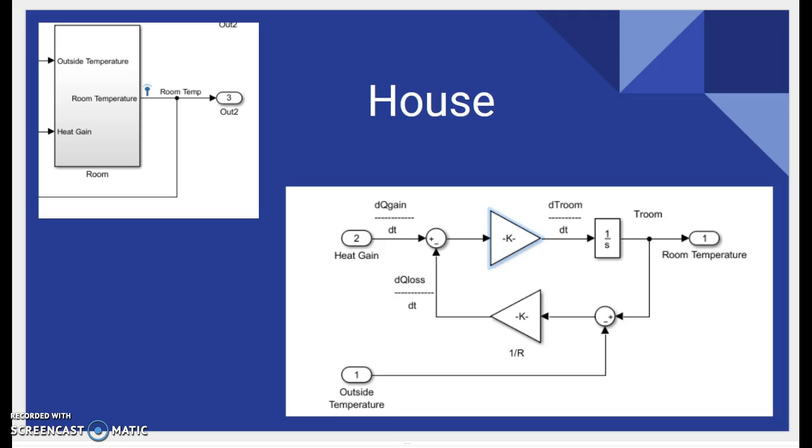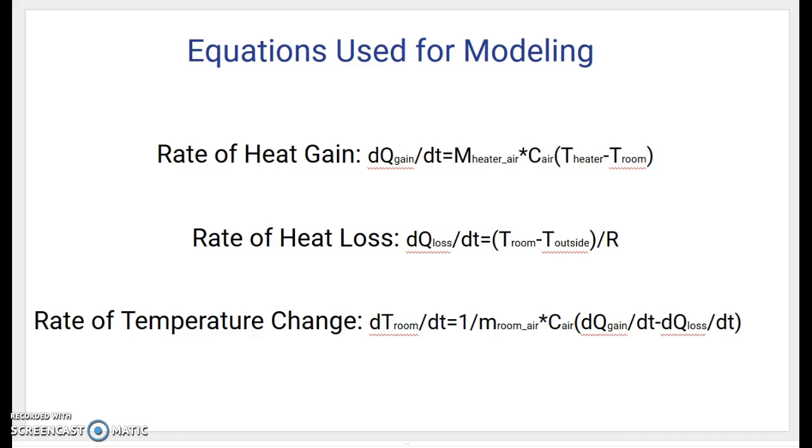The room temperature is continuously fed into the Simulink loop to either turn the heater on or off. The top two signals are measured inside and outside temperatures. The measured outside temperature was used in the Simulink model. As you will see in the temperature comparison chart, the measured inside temperature was used in the simulation.